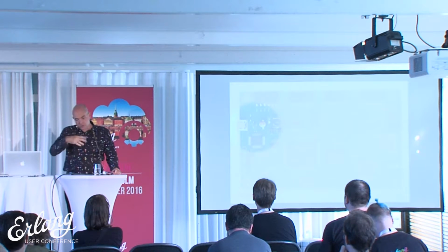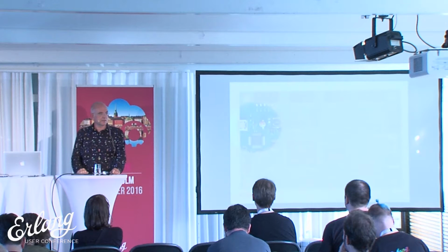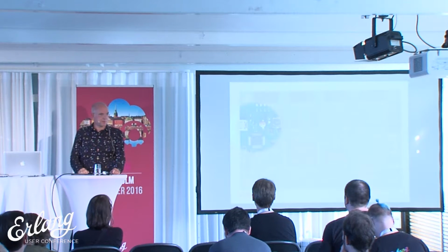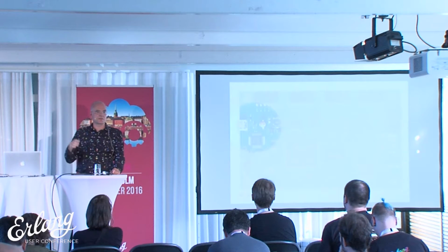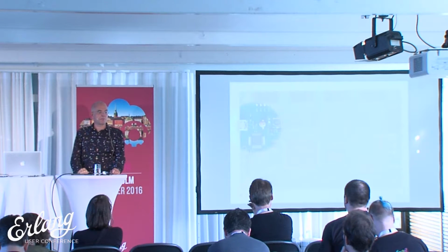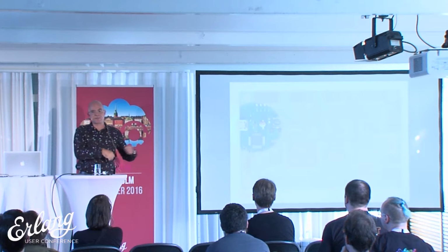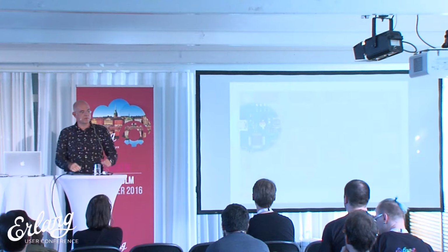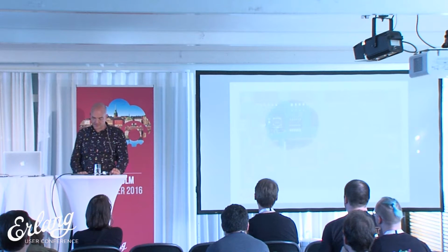You have to connect to the board and debug it somehow. So there's a USB connector to it, and it gets powered by the USB connector, so you can power it by your laptop. But you can also use a normal USB power supply, of course, or a USB battery. You can get all kinds of sizes of batteries, but you have to charge them separately. So you have one of those USB batteries, you charge it, you connect it, and it runs. The board doesn't have any charging electronics on it.